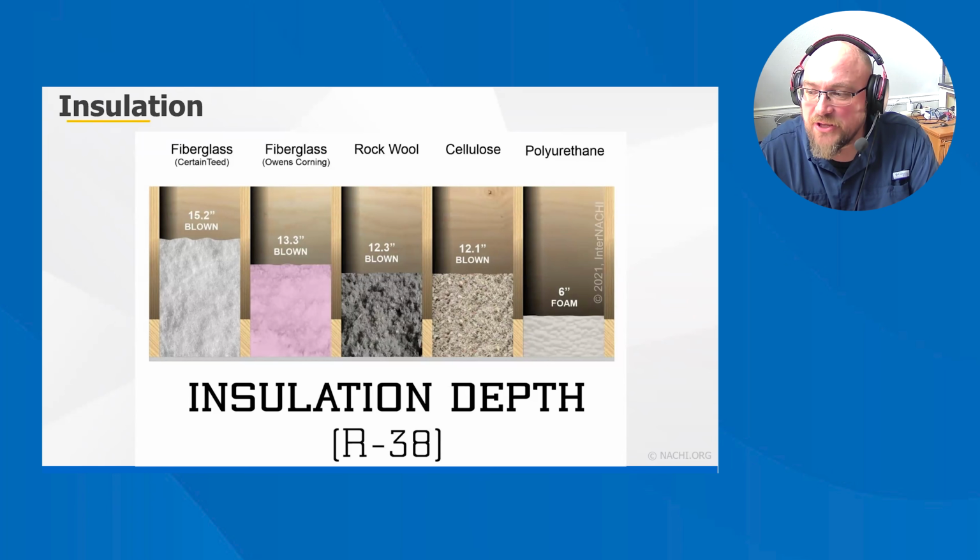The overall R value of a wall or ceiling will be somewhat different from the R value of the insulation itself because heat flows more readily through studs, joists, and other building materials, in a phenomenon known as thermal bridging. In addition, insulation that fills building cavities densely enough to reduce airflow can also reduce convective heat loss. The illustration shows how thick an insulation type must be in order to achieve the same R value.